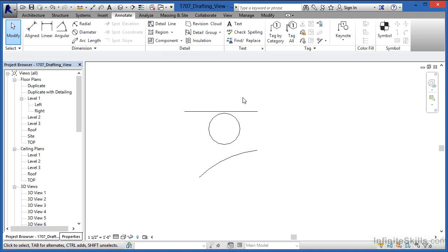views. Another use for the drafting view is if you have pre-drawn AutoCAD details. Maybe you've been using your other CAD software packages such as AutoCAD for years and you have your own library of symbology and details and that kind of information. Well, you can bring those into a drafting view, and then from a drafting view, those can get inserted onto your different construction document sets.